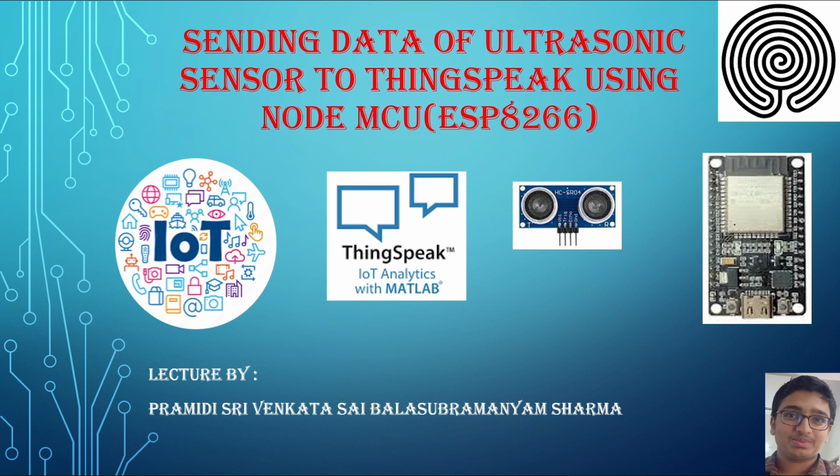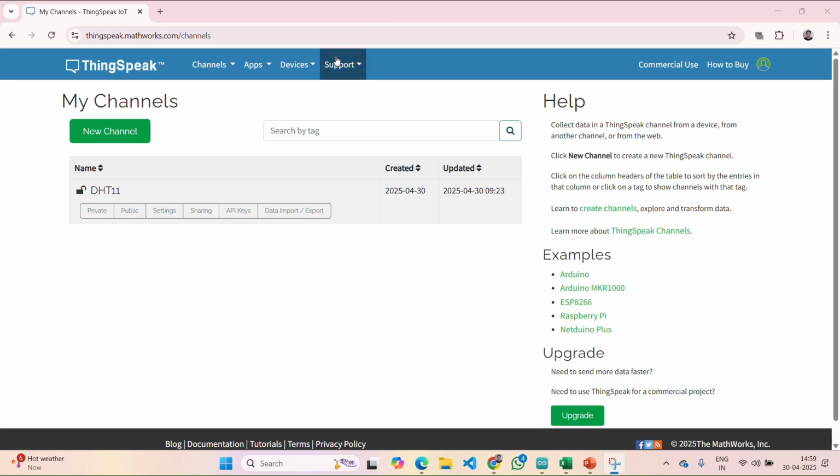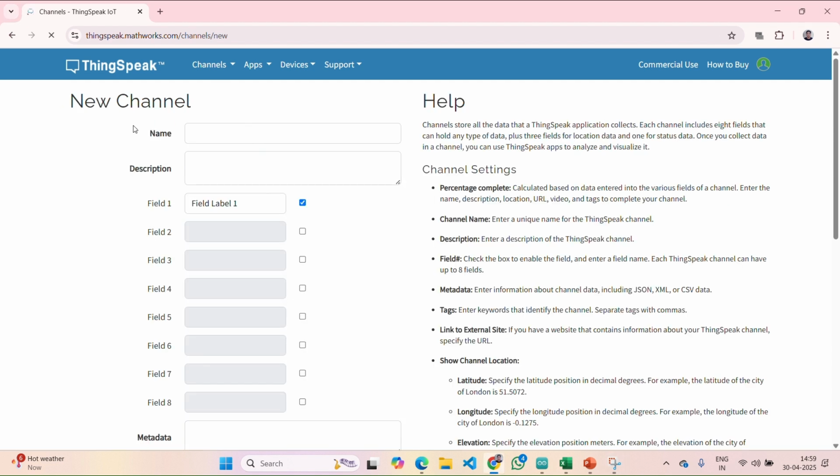Now let us see ThingSpeak first. So log into your ThingSpeak account, guys. In the previous lecture, we used the DHT11, right? Even now, you can use that same channel and consider any new fields or the same fields to send data. It's not an issue. But I want to maintain a new channel. Let me name it ultrasonic sensor